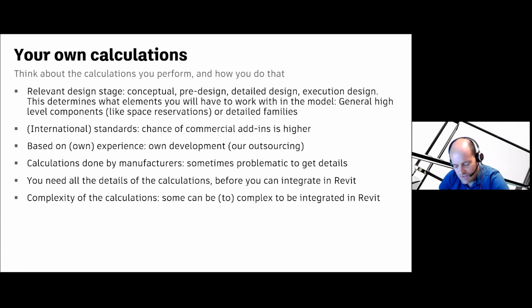Another pitfall can be the complexity of the calculations. If you have really complex calculations, I'm thinking, for instance, of sound calculations, it can be the case that it's simply too complex to be integrated into Revit. So certainly, if you have complex calculations, don't start with those. Start out with the easier ones, so that you get some experience on how you can integrate it, and then maybe make the step to the more complex calculations to be integrated in Revit.